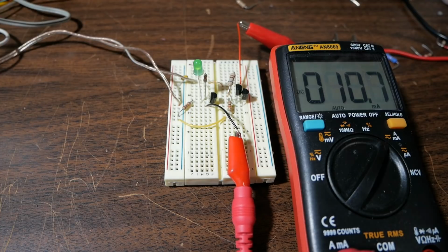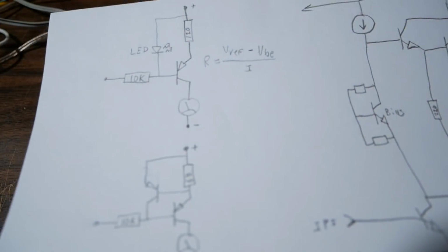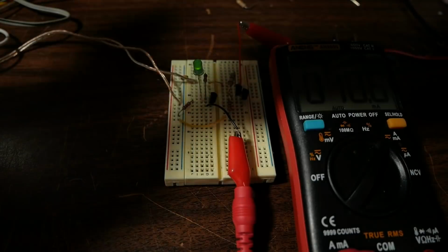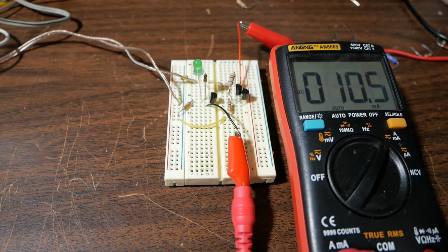Okay, now I'm going to adjust the power supply that's fed across the circuit, in other words from this point to this point, and we'll see how it affects the current. This is more important because it'll show the linearity of the circuit, and I also want to see what the dropout voltage is. So we're at 16 volts. I'm going to crank the power supply all the way up to 32. Okay, it's maxed out.